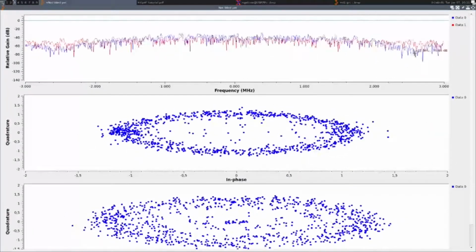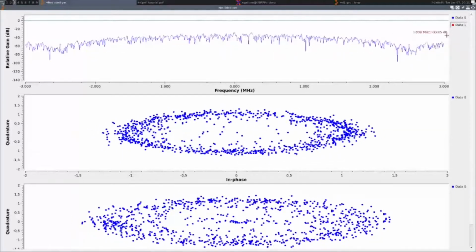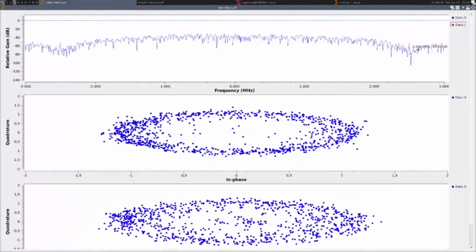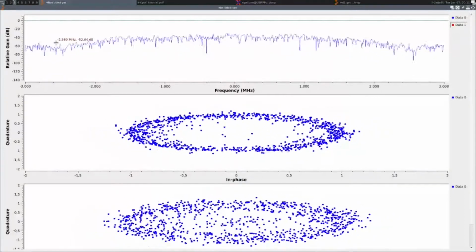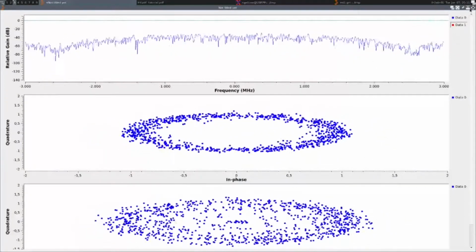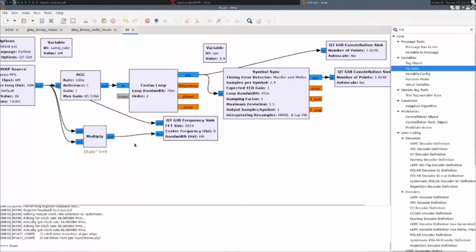Yet you still see on the blue chart over here the exact same spectrum as before, from plus 2.5 megahertz to minus 2.5 megahertz. So in terms of analog spectral occupation, we have the same state, but we've doubled the data rate.